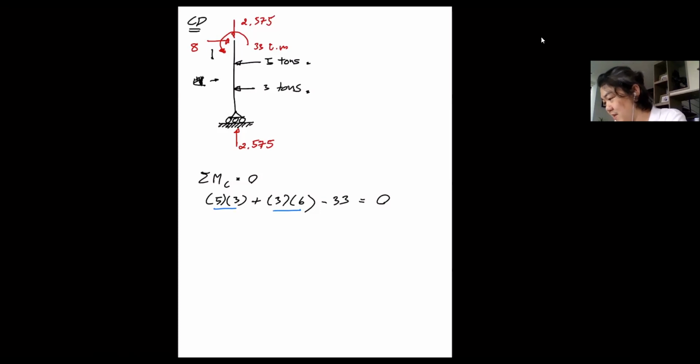Okay. So I see the positive shear now, right? Because I look at this direction. So this becomes my sign convention. Go up and then down. So it's a positive shear. Okay. So my shear force diagram, I begin from this point, point C. So it's a shear of 8 going to the right or going up in this direction. So it goes up 8.